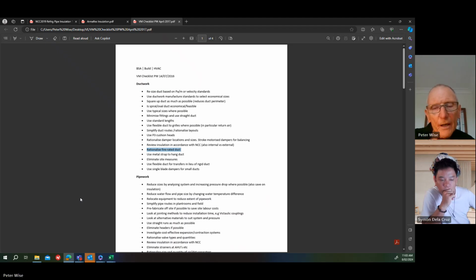They all have different requirements. And in Section E of the NCC, it tells you the smoke hazard management requirements for the different classifications and sizes of buildings. It might be a class 6 shop, but if it's only a very small shop, maybe you don't have to do anything.